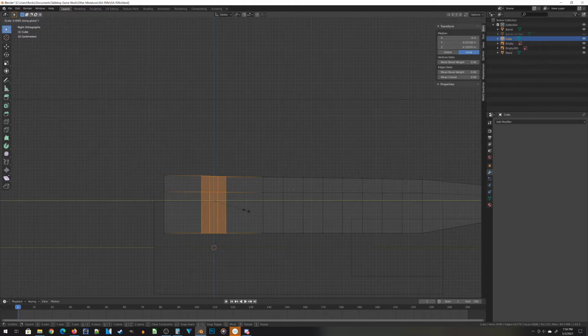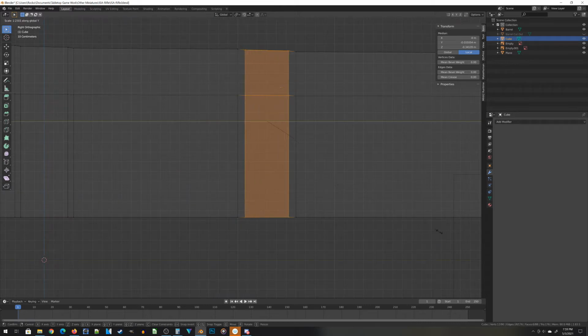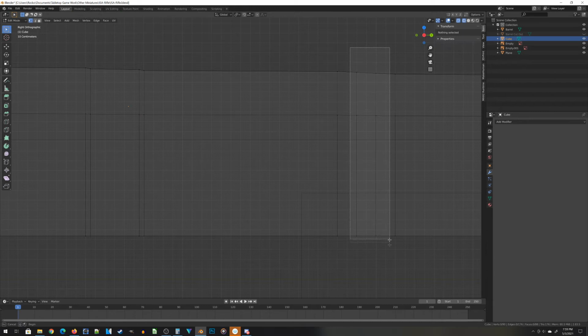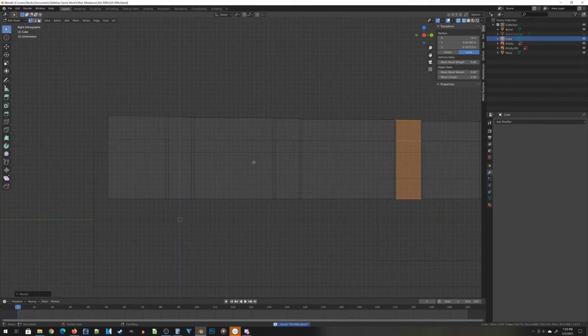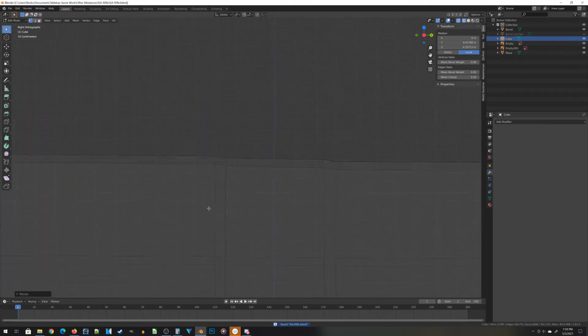After making these loop cuts, you want to bunch them into groups of 4 and scale them down so they're about 6 millimeters-ish, but the exact size is up to you. Then for each of the sets, push the 2 inside loop cuts pretty close to the outside. Now what you're going to notice once you do this to all 3 of these cooling vents is that the top of the barrel shroud is no longer nice and smooth because of all the scaling. So we got to fix that.